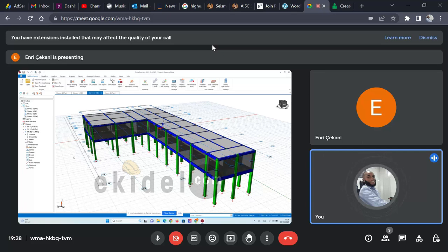You must consider the link and bar steel grade strength, or steel strength. And then you must also consider the arrangement of the vertical bars. That's for the columns. And then you must consider the shapes of the links for the beam or for the column, because if you don't use the right shape, it will also affect the strength of that member.